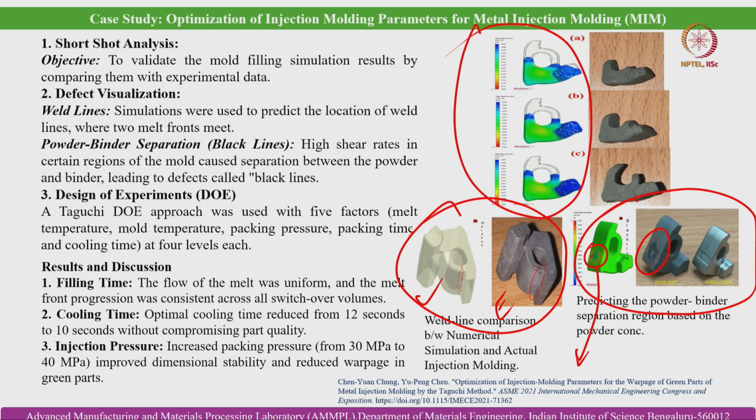volumes. And the optimum cooling time has been reduced from 12 seconds to 10 seconds without compromising part quality, and increasing the packing pressure from 30 to 40 MPa improved dimensional stability and reduced warpage in green parts.